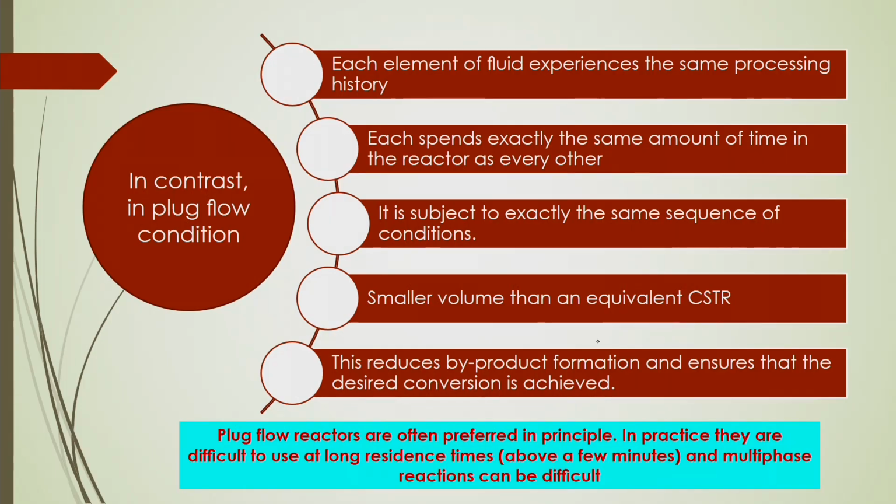Also, in plug flow conditions, smaller volumes than an equivalent CSTR will give you the advantage of yield of the reaction. And in plug flow systems, this will reduce byproduct formation and ensure that the desired conversion can be achieved. So, plug flow reactors are often preferred in principle.